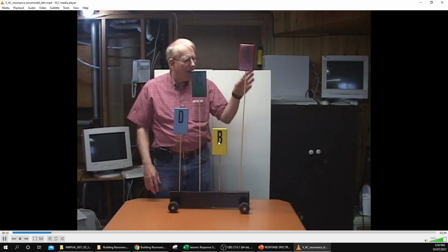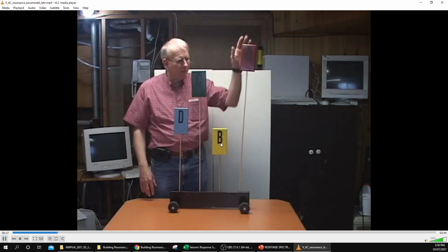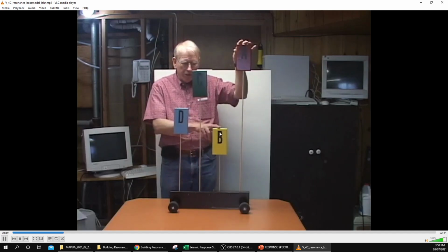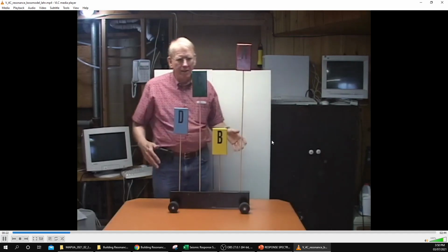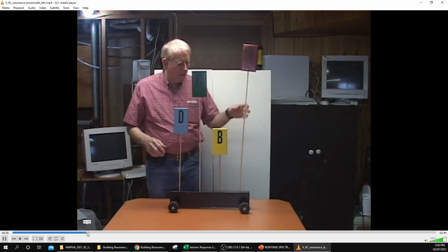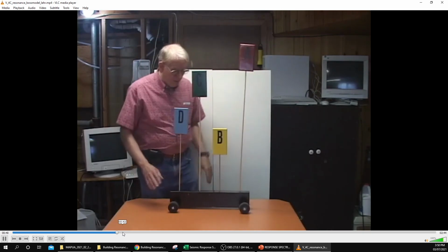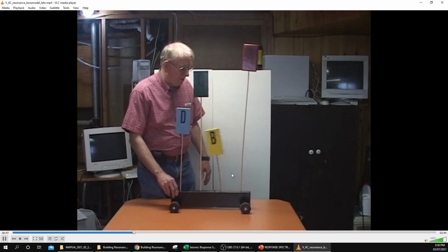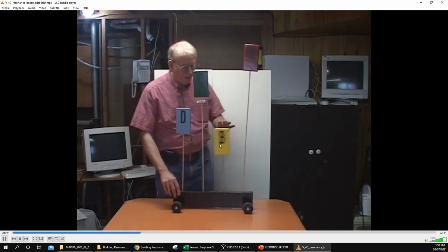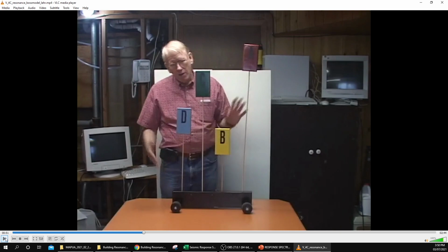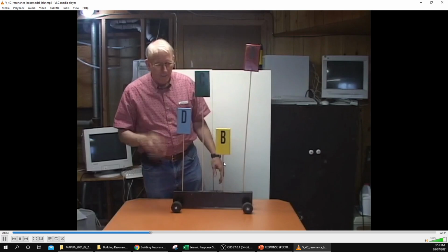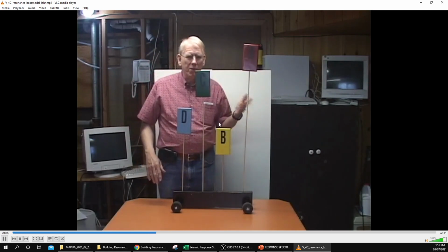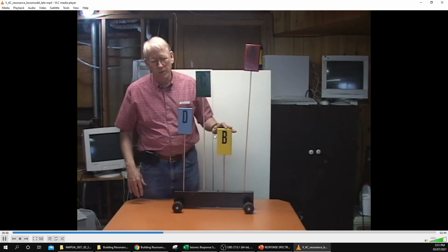Generally, the shorter the building is, the shorter the period. So we've got the tall building representation, the smaller height, the short building. He starts at a high frequency shaking, and the short building moves the most. So high frequency shaking or short period shaking will resonate with the shorter structures. Now a lot of people change their guess and say, well, I think maybe the short one will move the most.